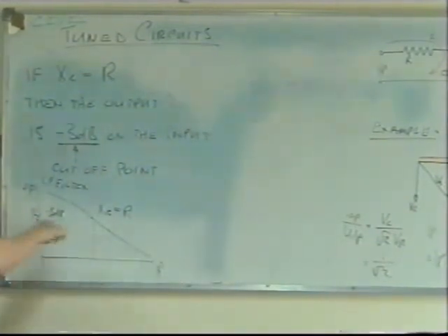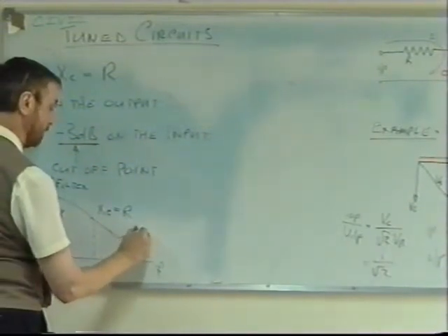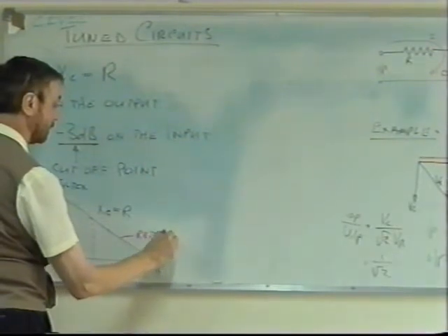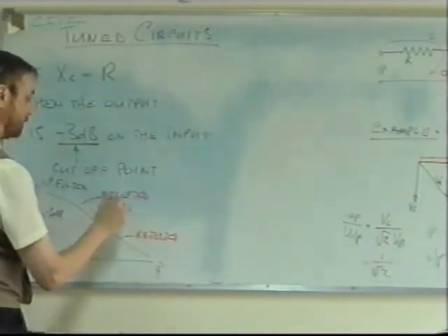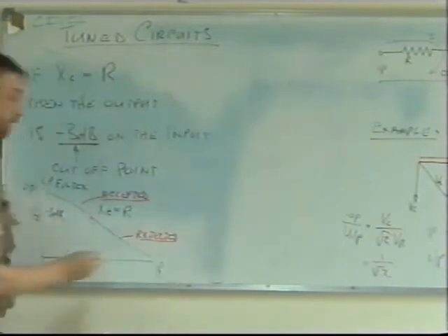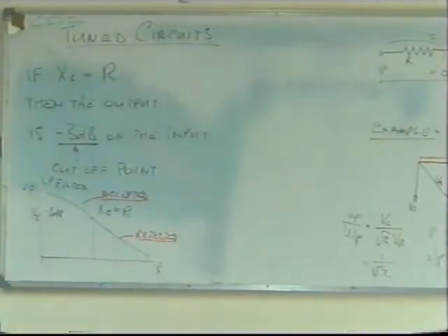So another way of mentioning this, as we mentioned the other week, is that these have been rejected and this has been accepted. I used those 2 words when we were talking about filters. If it's lower than minus 3 dB, then the signal is rejected. If it's higher, it's accepted. This is just a standard level, universally agreed to be what we call the half power point of our filter.